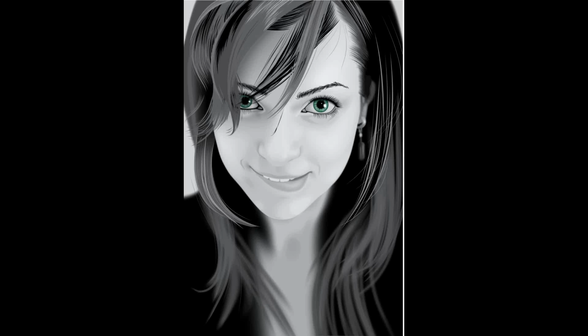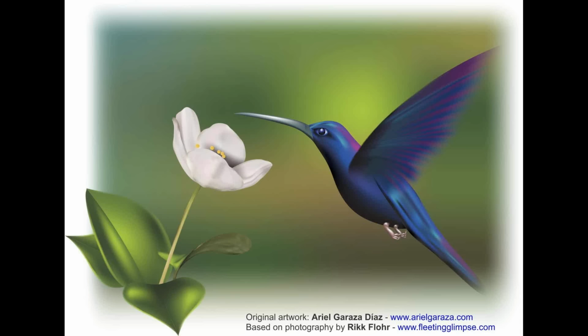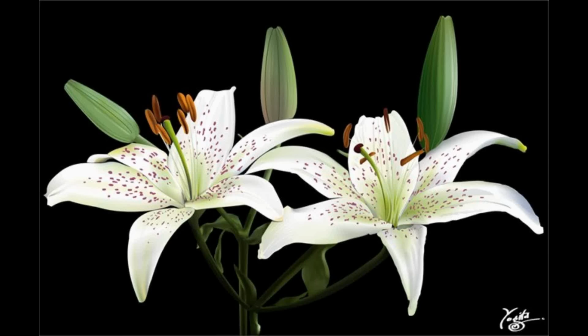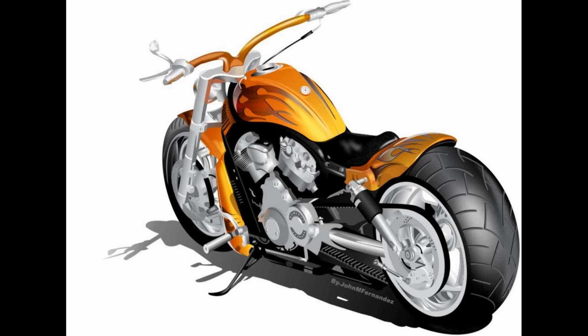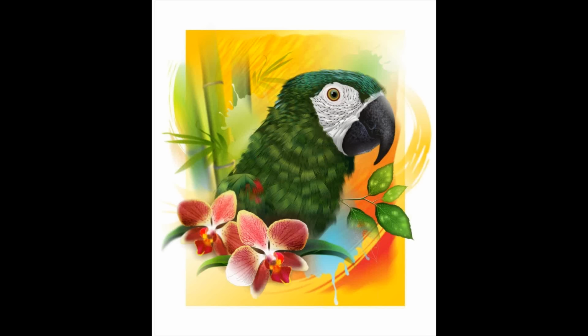You can add color to a patch inside a mesh fill and to the individual intersection nodes. The gradient will then spread out from those areas or points depending on the locations of nodes and lines around it. Moving intersection nodes allows you to adjust the progression of colors. In addition, you can smooth the color in a mesh fill to reduce the appearance of hard edges. You can also apply transparency to the mesh fill to reveal objects underneath. So let's start by creating a rather simple mesh fill.